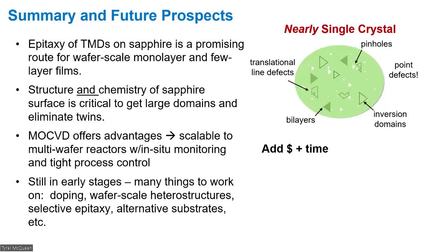But I should mention that there's a lot of work starting on selective growth of these materials. If you can control the nucleation on the substrate to a specific spot and grow a small enough domain there, then for transistor devices, you don't need to completely cover the surface. You just need your semiconductor material in a specific location. So there's work on patterned substrates, ways to control the substrate surface so growth occurs just where you need it. That way you don't have to do transfer.